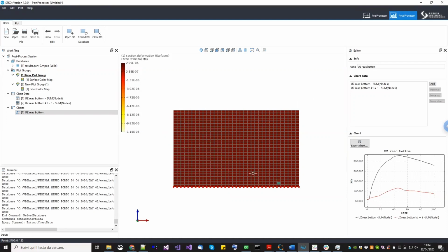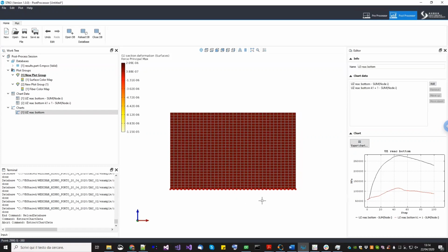So whenever you have a wall that is fixed and loaded in shear or loaded out of plane, that, as we have seen, generates a lot of shear in the mortar joints, transverse shear in this case, not in-plane shear, you can expect this kind of behavior. So try to calibrate that material parameter, okay?